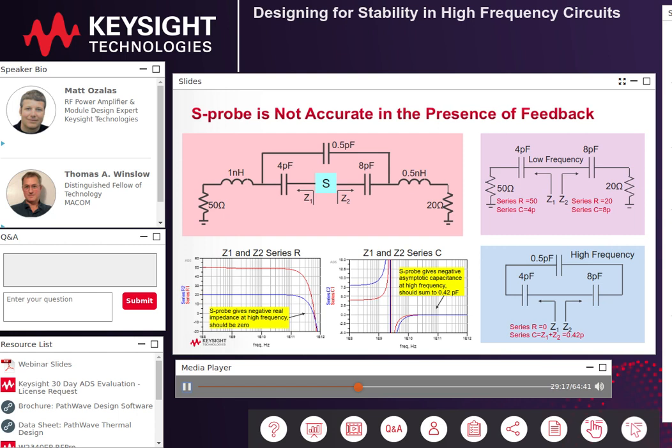The original S-parameter probe was proposed by Ken Wang at TI, published in 1992. It was developed specifically for oscillator analysis. Now, the S-probe that you find in ADS is a modified version of Ken Wang's approach. The problem with all current attempts at in situ impedance probing is that they either perturb your circuit or they're mathematically unstable and thus inaccurate in the presence of detectable amounts of feedback. But this has all been resolved with the new WS probe in ADS 2020.